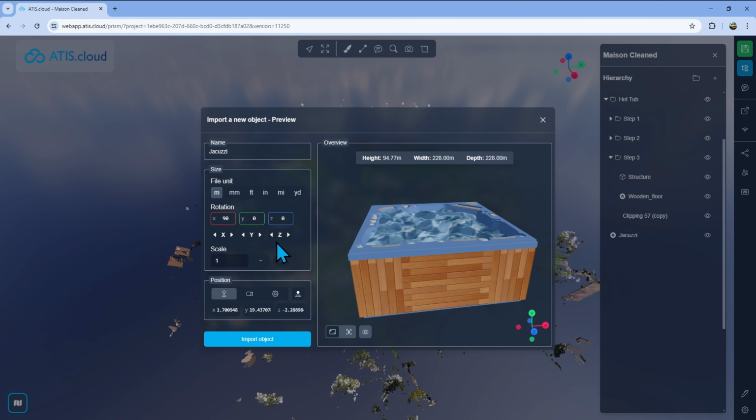So let me just select the whole thing, movable, move the folder, and try to move it down. Okay, so that's where it's going to go, and oh, there's a problem. As you can see, right here, I have my clipping box from the garage door that is actually cutting the roof open, because this little vertical pillar that I have right here is not going far enough inside. Now I could just decide to have this being wider, but then it wouldn't fit with what I have right here. So now what do I do?